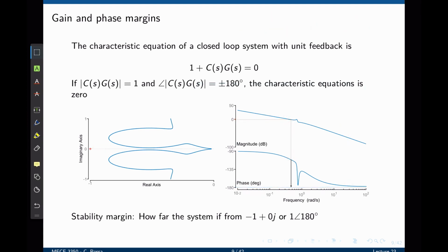And this is a good example to visualize how important it is to define gain and phase margins. The gain margin appears to be infinity, but if you look closer at this transfer function, even though it is closed loop stable, it is very close to the critical point that may lead to instability. If a gain margin is positive, that means that that amount of decibels can be added to the closed loop transfer function before the system becomes marginally stable. The system as it stands then is closed loop stable.